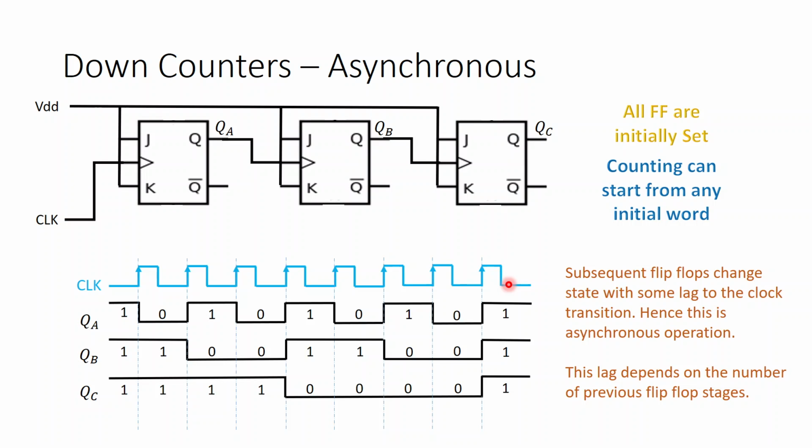Of course, it can also be set up with a JK flip-flop like this. The only thing we need to understand is basically the connection of the clock signals of the subsequent flip-flops. For the initial flip-flop, the normal clock is connected. For the subsequent flip-flops, what is the clock signal there, that is what we need to keep in mind.